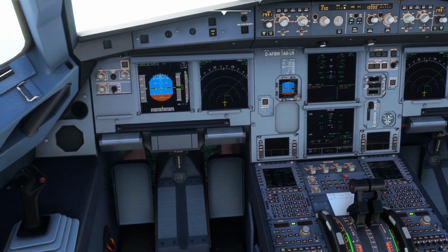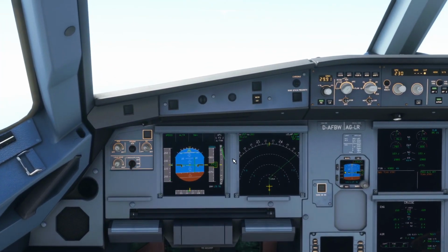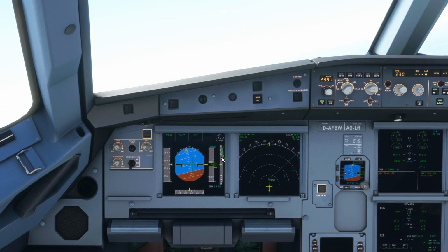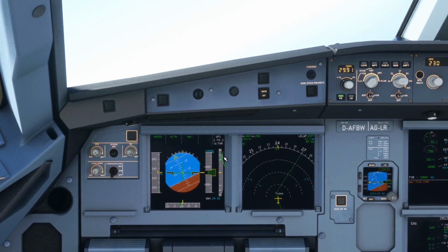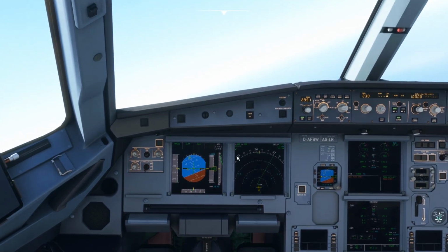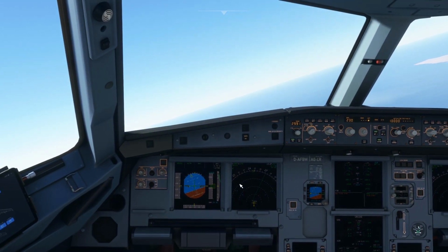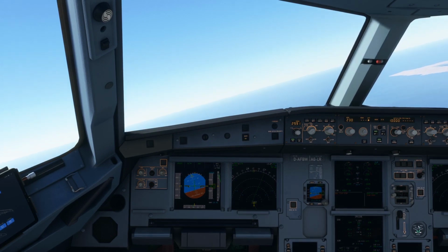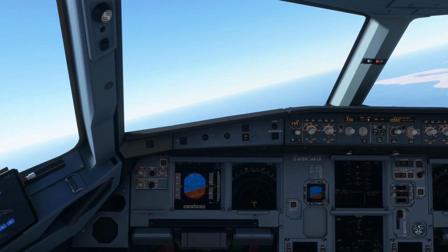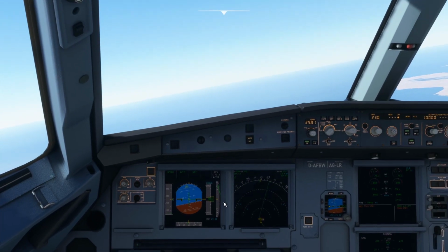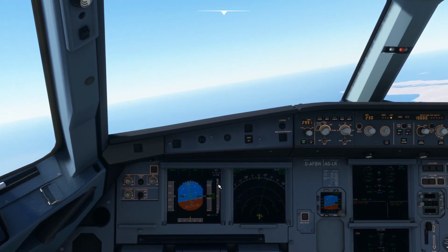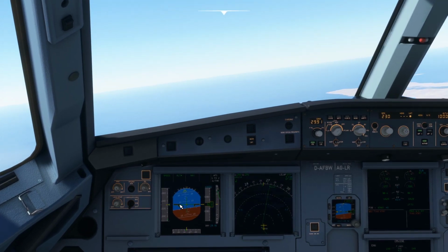So after the takeoff, you have to actually adjust your vertical speed in such a way that your plane does not exceed 230 knots. Right now you can see over here your vertical speed is 35, which means 3,500 feet per minute. So if you increase your vertical speed, your ground speed is reduced. Obviously, if the plane is climbing up, it cannot go really fast. So you have to basically compensate your speed according to that. So I was also trying to increase the vertical speed, or the climb rate of the plane, so that the speed is under 230.